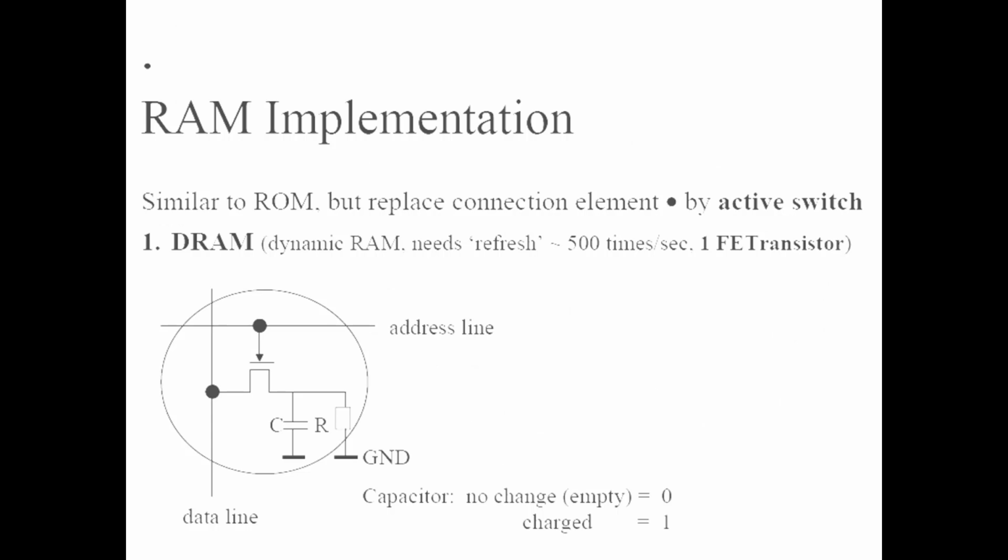Here's how it works. So we have the components of the 1T-DRAM. Number one, transistor or the FET that acts as a switch to control access to the capacitor. Number two, capacitor that stores the data in the form of electrical charge. And in terms of the working principle, we have the write operation, read operation, and the refresh operation. Write operation: when writing data, the transistor is turned on, allowing charge to flow to the capacitor. A high voltage or logic 1 or low voltage logic 0 is applied to the bit line and the corresponding charge is stored in the capacitor.